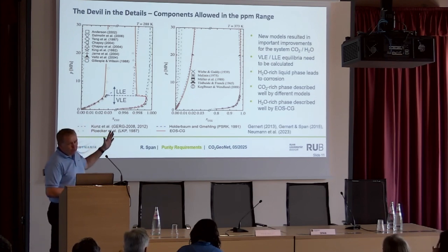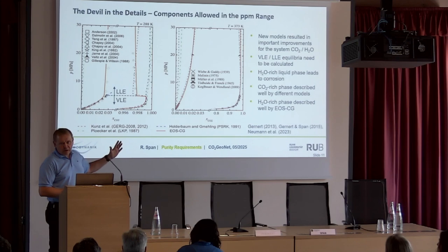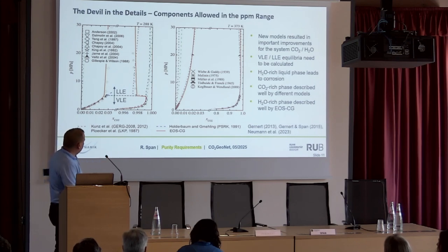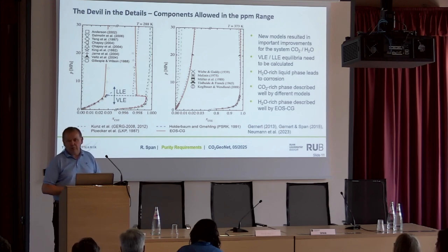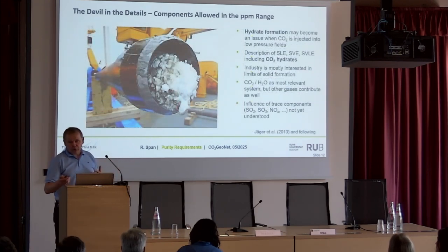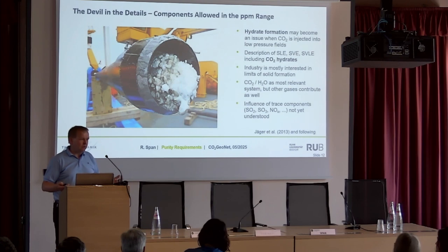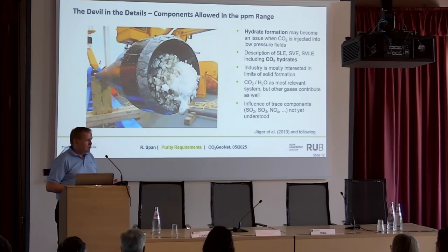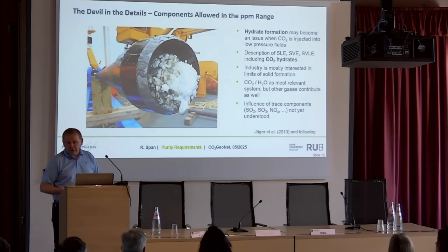For the water-CO2 system, we have a pretty good understanding, so there aren't many open questions. But we are still talking about a few hundred ppm or even 1,000 ppm when we only have the system CO2 water. The only thing that might be relevant for storage at that point, because your reservoirs contain water anyway, is hydrate formation close to the injection site when the temperature drops.